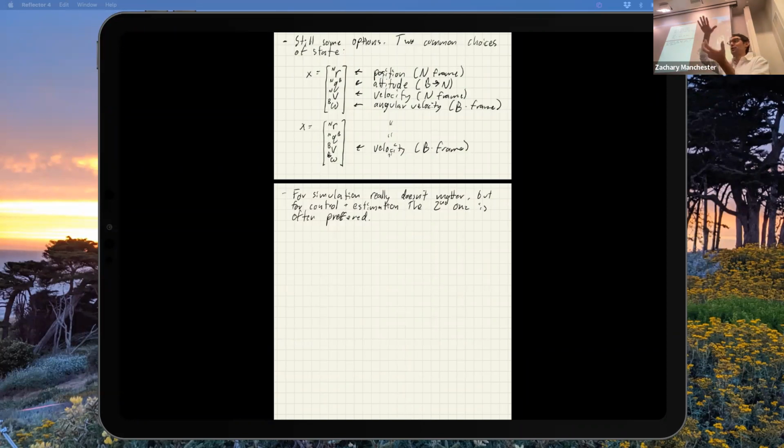What you're basically doing, if you think about it, is the dynamics are moving around on this sphere. Remember the quaternion kinematics? The invariant trick is you do it on the Lie algebra, which is always the tangent plane at the North Pole. So the North Pole tangent plane is constant, doesn't change. And you use the kinematics trick to move the tangent plane around outside of the filter. So now the filter equations are always at the North Pole tangent plane, and so they stay constant, they're invariant, which is pretty slick actually. That's kind of cool. Okay, so any questions about that?